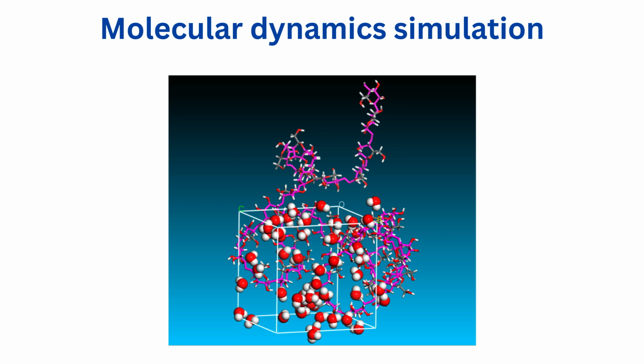Molecular dynamics simulation is among the most successful methods for modeling polymer networks through a reactive scheme. It accounts for the stiffness of prepolymer chains through explicit force field parameters such as angular and torsional potentials, steric hindrance of surrounding chains, which affect reactive groups' accessibility, and the evolution of the spatial arrangement of chains and crosslinkers during the reaction. Therefore, various researchers employed molecular dynamics-based reactive schemes to construct a reliable network structure, able to predict many properties that were in good agreement with the experimental results.